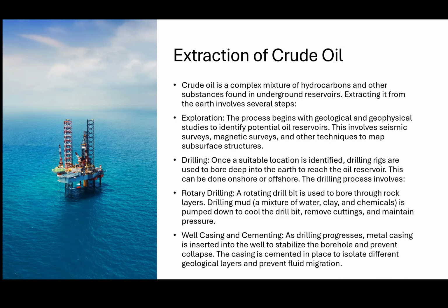The drilling process involves now rotary drilling, right, where a rotating drill bit is used to bore through rock layers. Drilling mud, a mixture of water, clay, and chemicals, is pumped down to cool the drill bit, right? So remember, we're continuously rotating and drilling into rock, so the amount of friction would create a large amount of heat energy, right? So we just pump drilling mud, which is water, clay, and some chemicals, to cool the bit, removing cuttings and maintaining the pressure in the area as well, right?